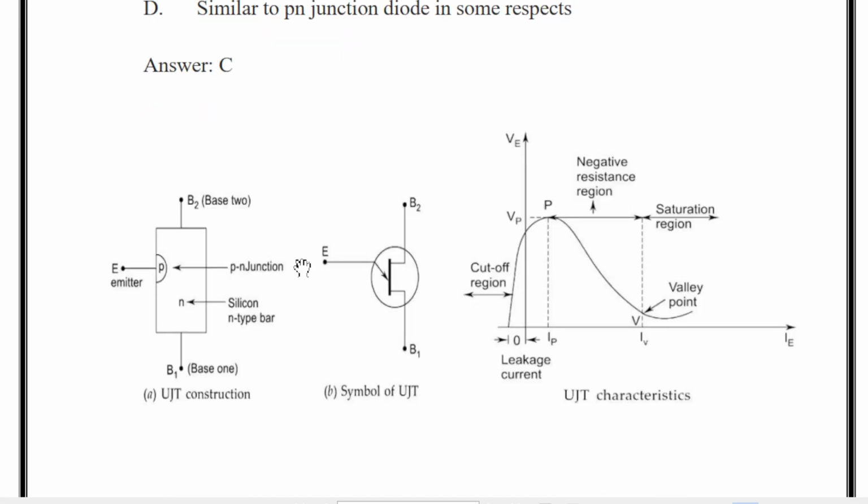Now you can see the unijunction transistor, UJT. A UJT is a three-terminal semiconductor switching device. This device has a unique characteristic that when it is triggered, the emitter current increases regeneratively until it is limited by the emitter power supply. Due to this characteristic, the UJT can be employed in a variety of applications, for example, switching, pulse generators, and sawtooth generators.